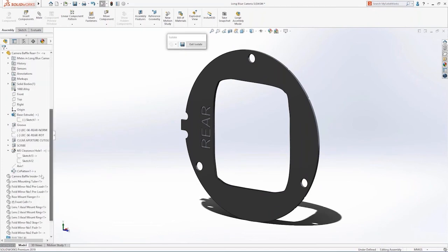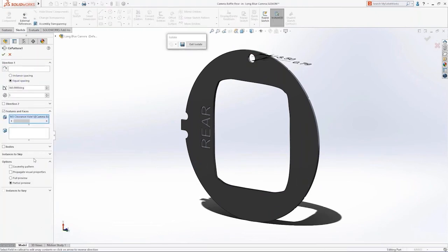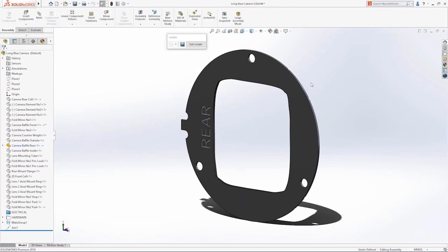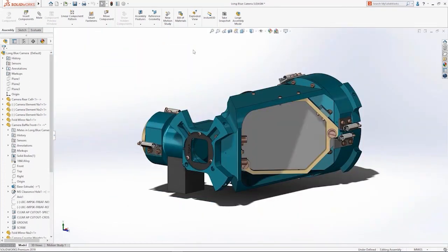It's going to show up as broken with that little X there. And so that's where it's just telling you this doesn't have a reference anymore. Definitely make sure you do replace it because we don't want ambiguity in our models. But then you can go ahead and replace it, you can fix it, and that's a great tool to replace those external references so that you can maintain that large assembly performance.